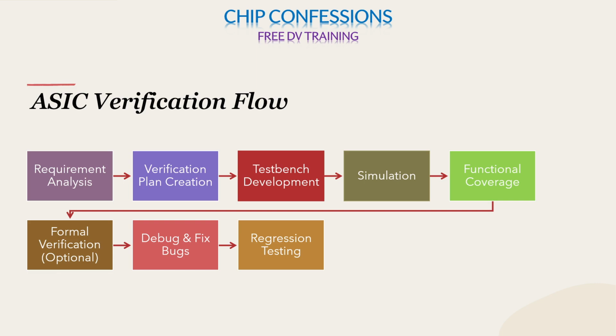Another situation is when some minor changes are made in the code, and then we have to check; there we can employ regression testing. As I said, we will run all the tests repeatedly whenever there is a change in the RTL code. It ensures that after fixing the code, it is not breaking or breaching the specifications. And then next is the sign off.